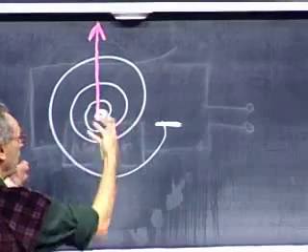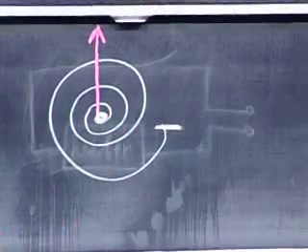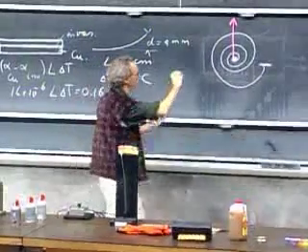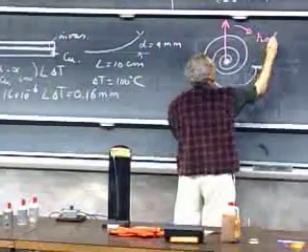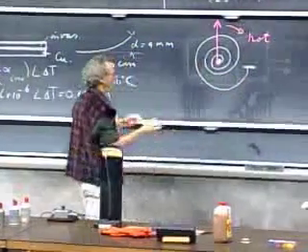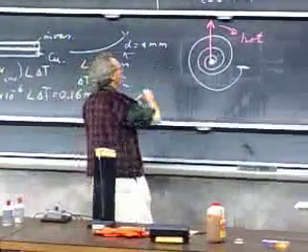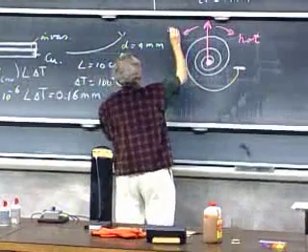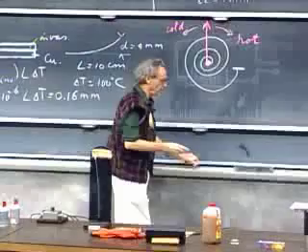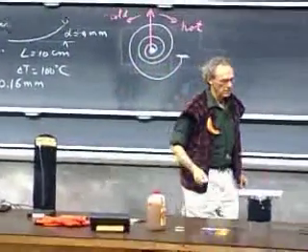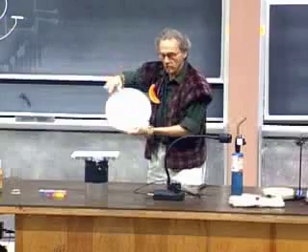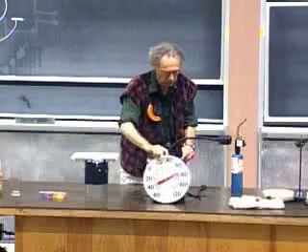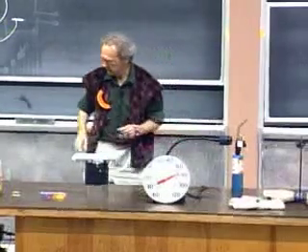It's already curved. But when I heat it up, it will tighten even more. It will curl up even more. And when this one curls up even more, it will go into this direction. So this is when the temperature increases. And when it, of course, gets colder, it will uncurl, and so here is cold. And that's what the whole thermometer is based upon. And in the back is this coil. And so I broke one open for you in order to make you see that coil.